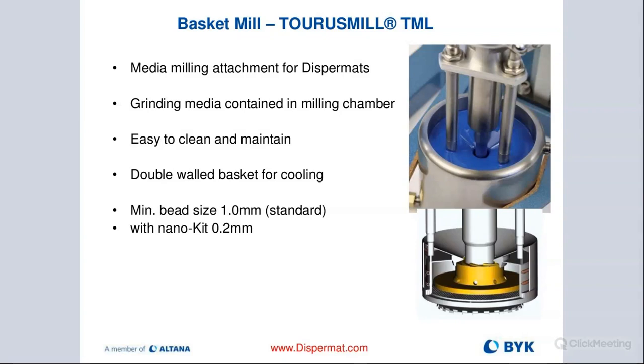And if we have a screen on the side, number one, we can't really cool it properly. But a much bigger problem is the wear on the screen, because this is where all the beads will impact if the screen is on the side. So you would see very high wear of the basket mill if you have a design like that where the screen is on the side.